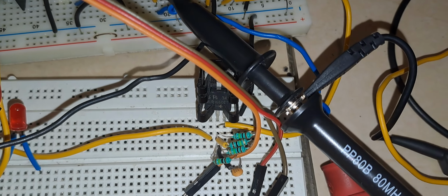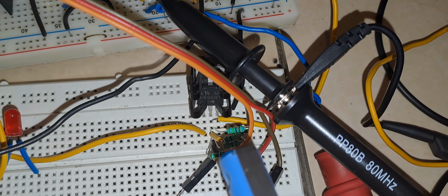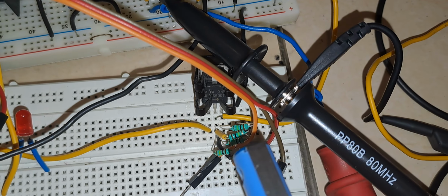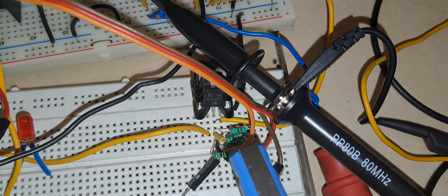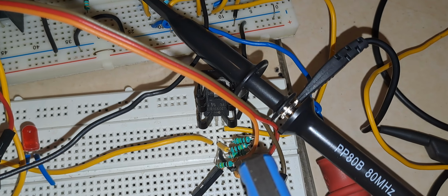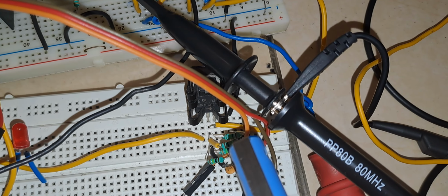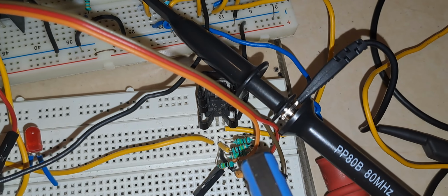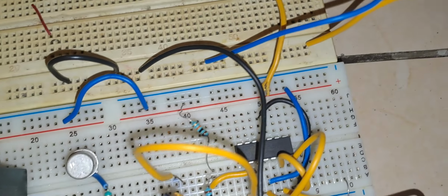This is an enhancement to the previous video. In the previous video I was using 100k resistance, and as a result the waveform was getting very bad. The capacitor was not able to discharge properly within the time and it was showing bad results. So in this video, this is an enhancement. I have increased this resistance. It is 25k now and the results are satisfactory. The output of this envelope detector is fed to an op-amp IC.